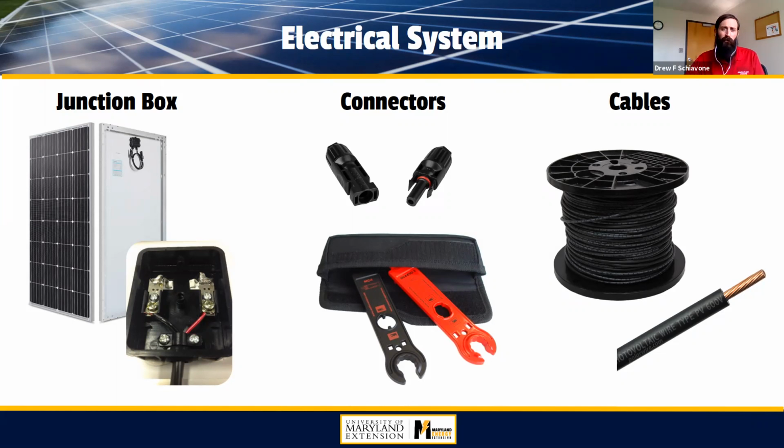And for a lot of applications, you're going to need a master electrician to do this. But if you're looking at some systems, you can do it, or if you're a do-it-yourself kind of person, there's options out there. What you'll see most common is these MC4 connectors. Those have a locking mechanism. You need a little tool to unlock them, the male and female ends, but those go on the end of your cable.